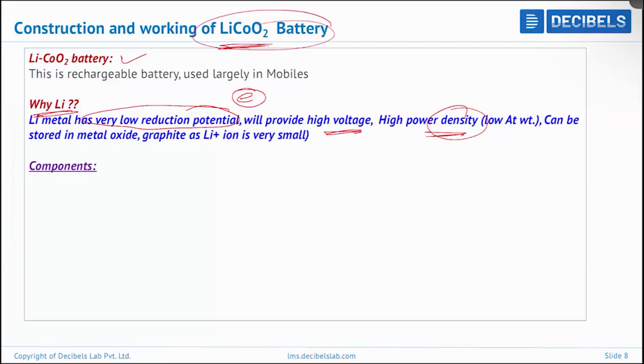This lithium cobalt oxide battery, as I mentioned, consists of anode, cathode, electrolyte, separator, etc. On the anode side, copper is the current collector, a thin film, and it is coated with graphite powder, represented by C6. The graphite powder is made into a slurry on the copper foil, then coated and dried. It's just graphite and some binder coated on copper foil.